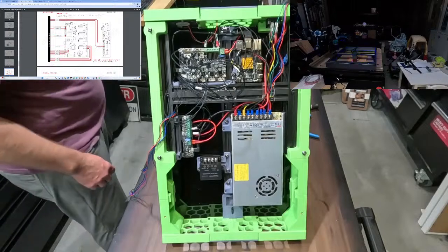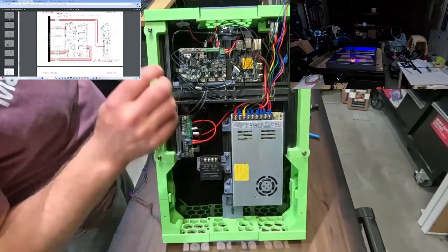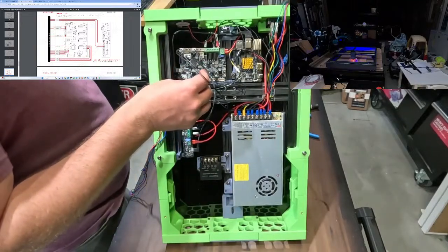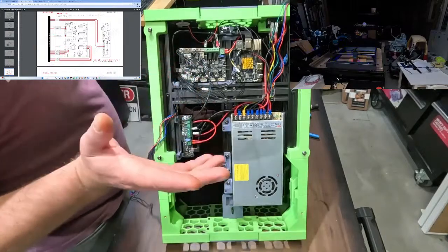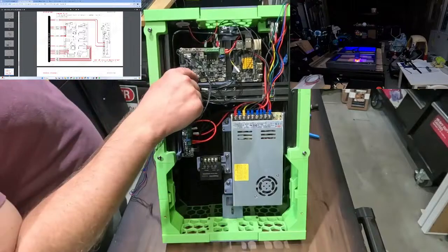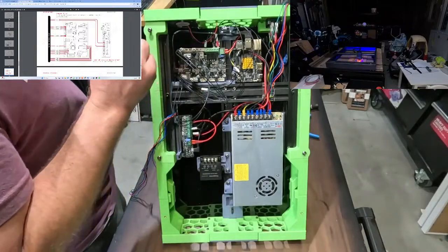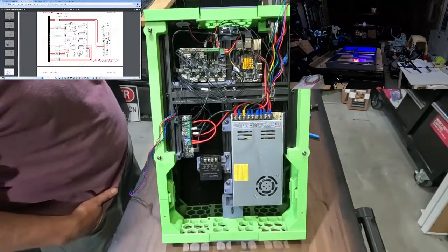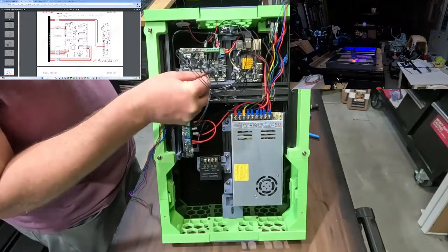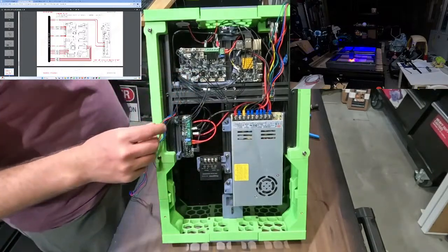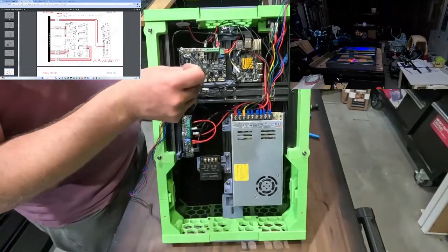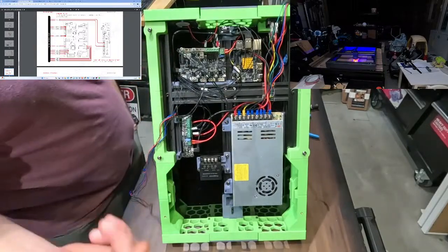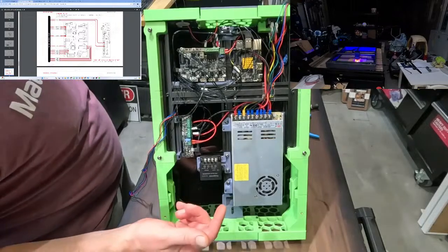And then we have our extruder stepper motor, which is connected up to that first terminal. The extruder stepper motor is kind of interesting. I don't know if it's wired incorrectly. I just let it ride, but the wiring says that it is incorrect. We'll play around with that when we actually get this thing hooked up. I hope it does not short anything, because this is just a wiring harness that goes up to the actual control board. As long as they go to the appropriate input port on the control board, it doesn't really matter what these cables look like, and the stealth burner is what I'm more concerned about.